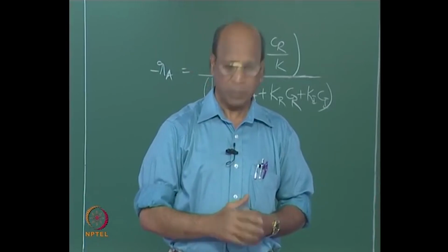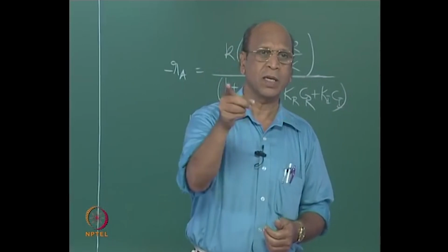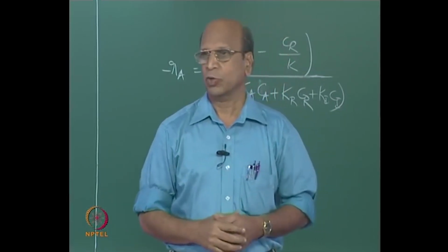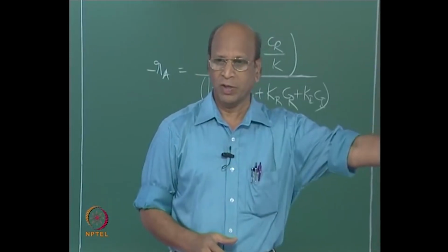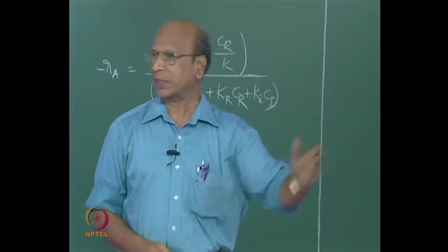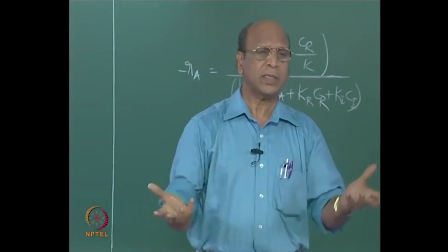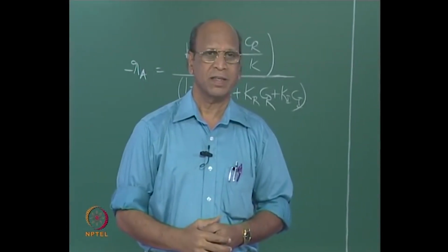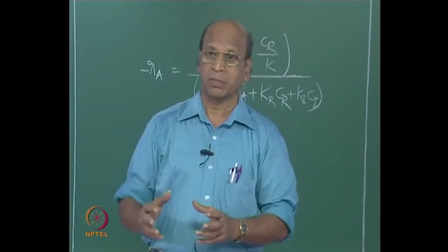Then in between you draw the number of steps; one step equals one stage. So, 10 steps means 10 stages. Now you go to Murphree efficiency and say, okay, if it is 50%, then you will get 20 plates. Where is mass transfer coming in there? That is also bad for you. That means you do not know what is really happening in the column, but still you could design.